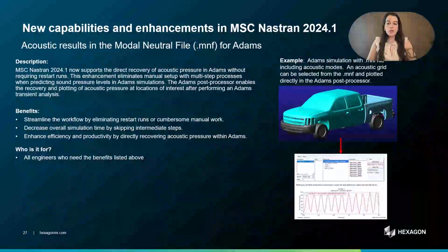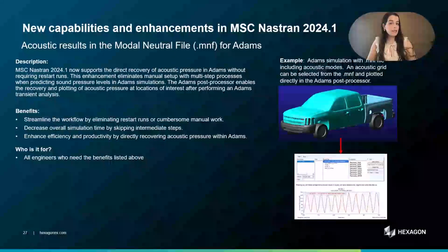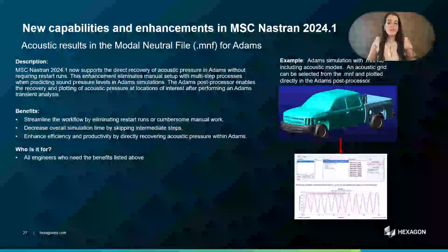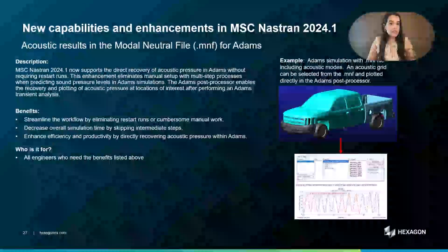The Adams post-processor allows the recovery and plotting of acoustic pressure at locations of interest after performing an Adams transient analysis. This streamlines the workflow, decreases overall simulation time by skipping intermediate steps, and enhances efficiency and productivity by directly recovering acoustic pressure within Adams.